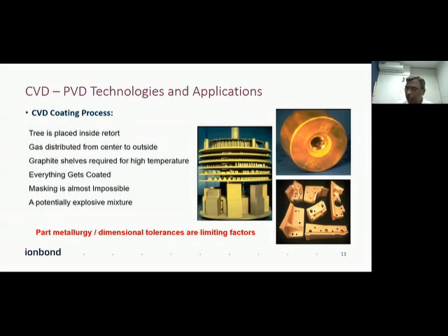In India, Sandvik, Seco, Tungaloy, Kennametal, all those who are manufacturing inserts, are using the CVD process for coating on carbide inserts only. For steel substrates, it is very little used due to the temperature limitation.